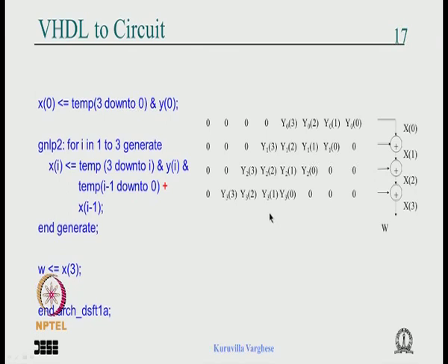So it is a multiplier, but not an iterative multiplier, it is a parallel multiplier, and the name of this multiplier is array multiplier because you form an array of the partial products and add them in parallel. So it is a 4 bit unsigned array multiplier. Only thing is that normally when you refer to the textbook, to avoid the rippling, carry save adders are used instead of a ripple adder.